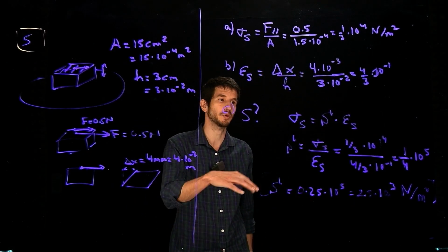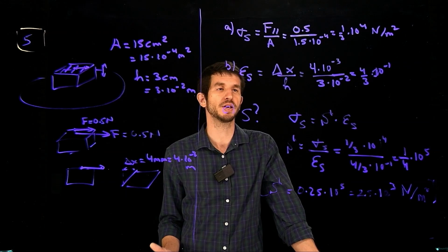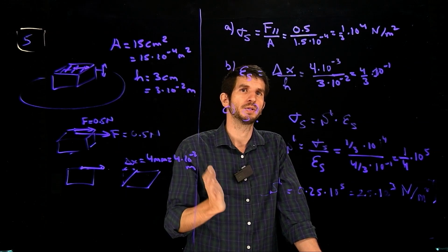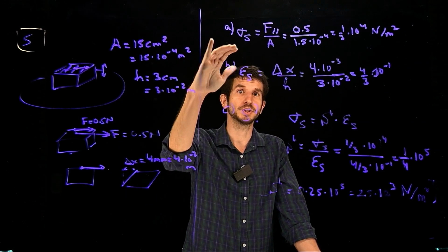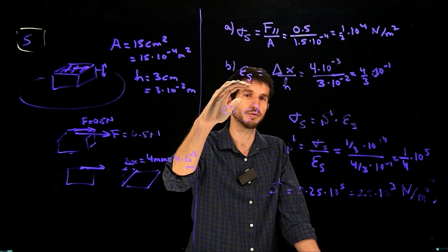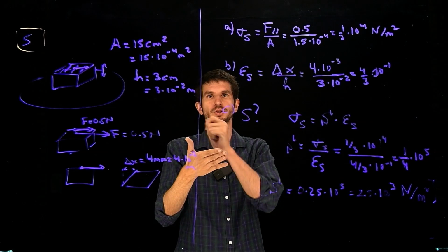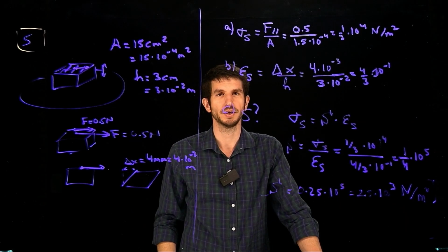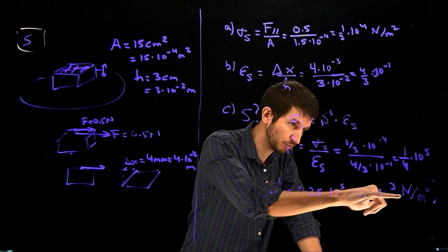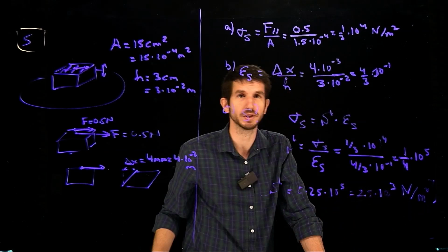So actually, this is how you would measure the shear modulus of something. Apply a force that you know over an area that you have calculated and determine the stress, then also characterize how it deforms, and from those you actually derive this. And then you would go to your handbook and write down, for this gelatin, this is the shear modulus, 25 10 to 3, so 25 kilonewtons per square meter.